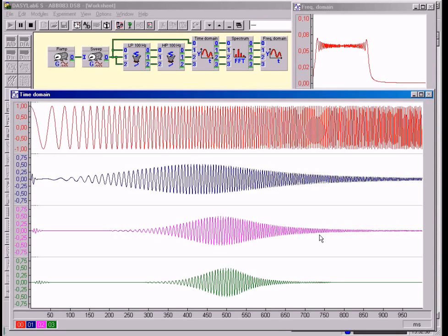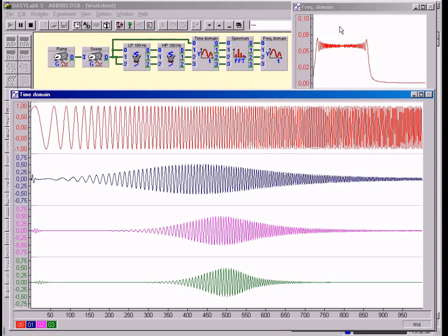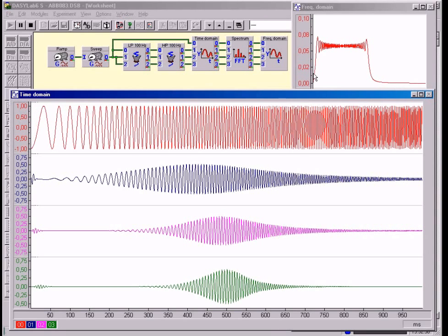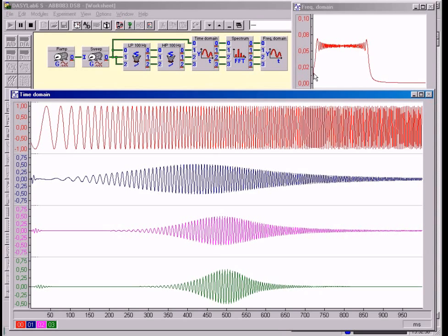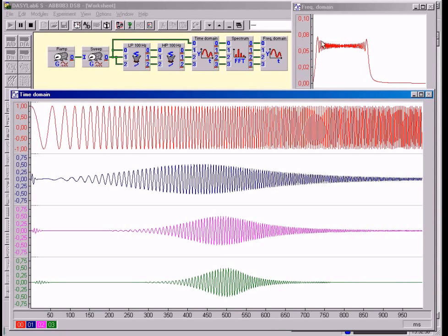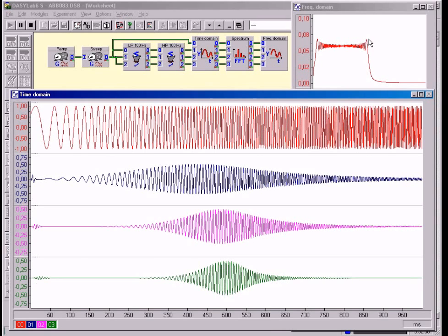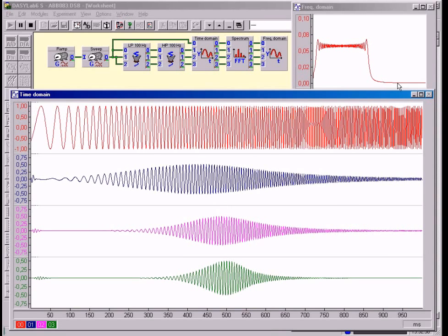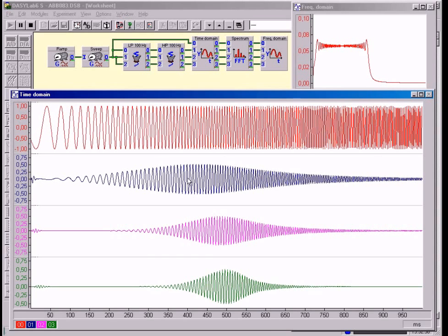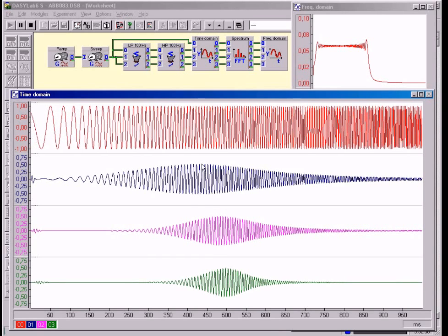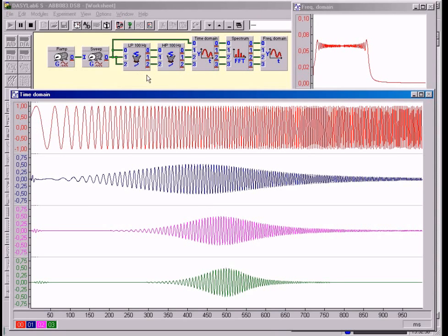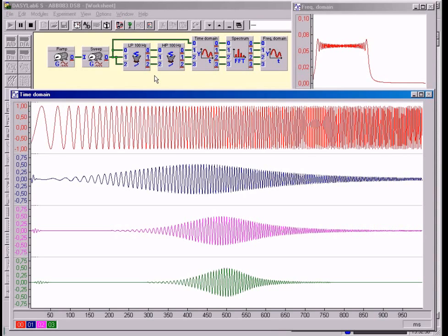But be careful. Never forget the uncertainty principle. The Fourier transformation of this sweep signal shows the consequences of beginning a signal suddenly, changing rapidly and ending abruptly. In this illustration, the sweep measurement is carried out using band-pass filters by adding low-pass and high-pass filters with different bandwidth, but with the same center frequency.